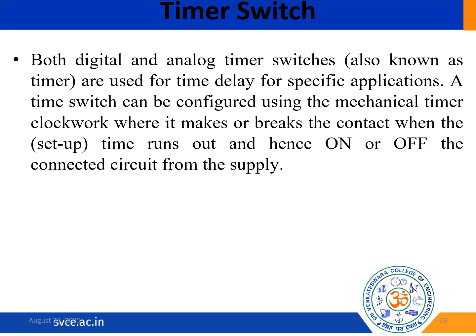These timer switches are essential for precision control. They can be used in automation and in energy optimization across residential, commercial, and industrial domains. Till now we have learnt about timer switches, which are available in both analog and digital formats. They are mainly designed to introduce time-based control into electrical systems, operating by delaying or scheduling the activation or deactivation of a connected circuit based on a predefined time setting. That's all about today's lesson.